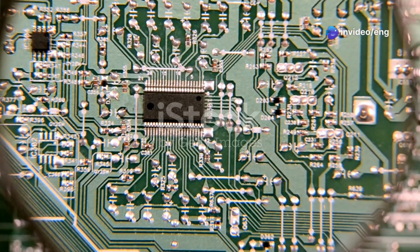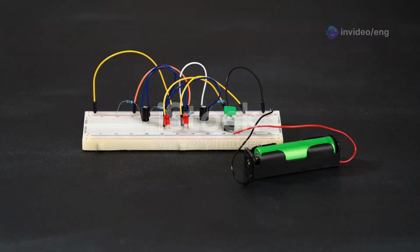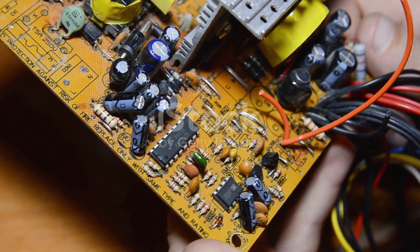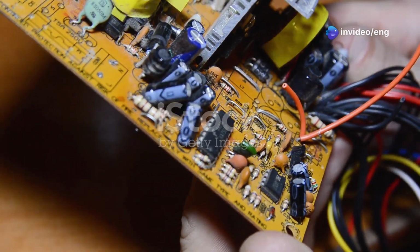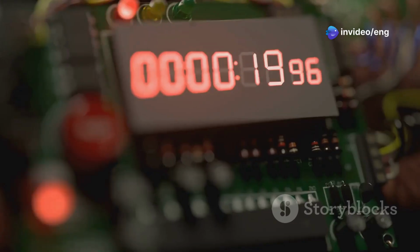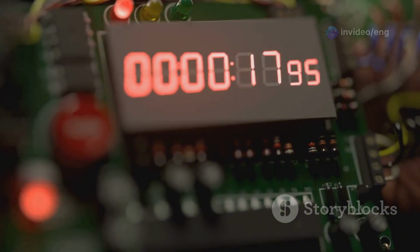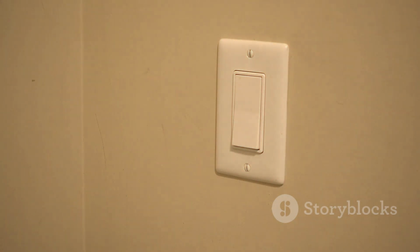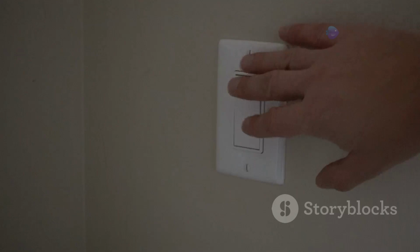Hey there, memory masters. Remember latches? They're like flip-flops, but with a slightly different way of remembering information. We'll start with the SR latch, similar to the SR flip-flop. It has two inputs, set and reset. The key difference is that the latch's output changes immediately when its inputs change. It's like a really responsive light switch that turns on or off as soon as you touch the button.